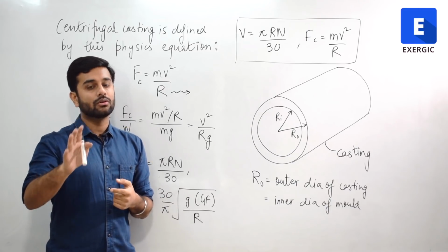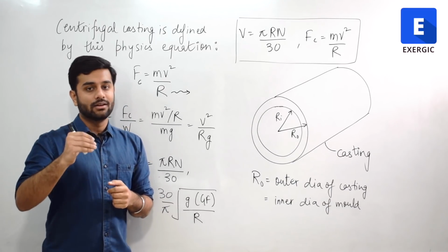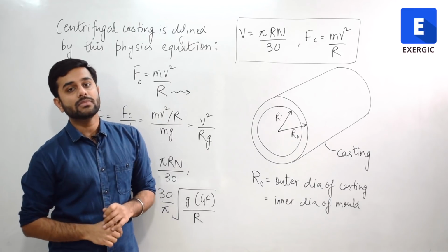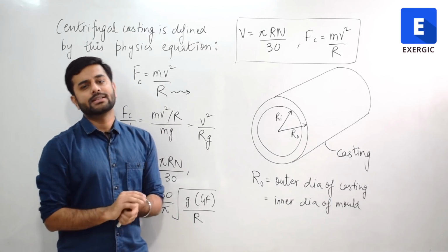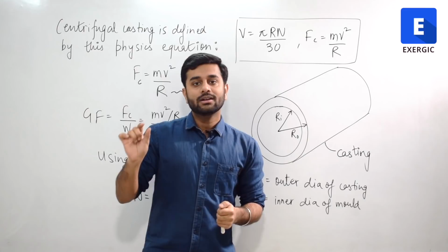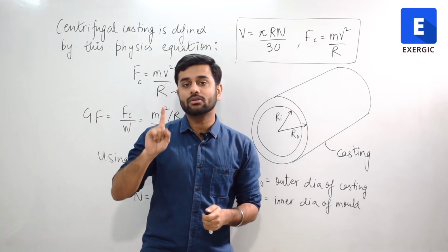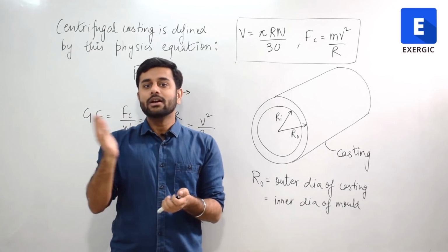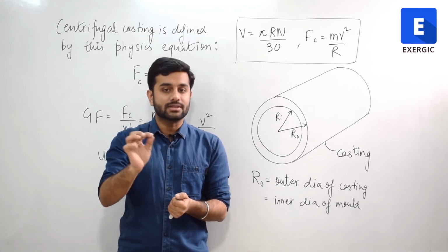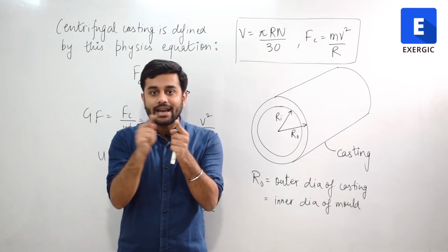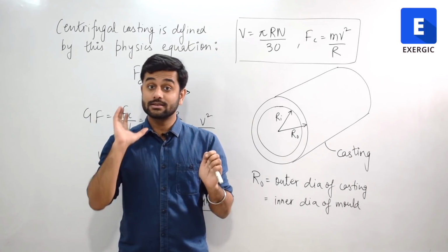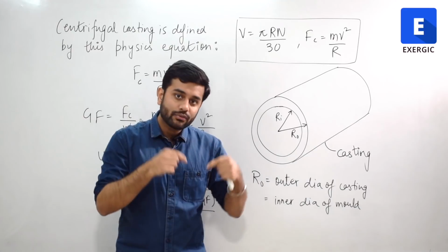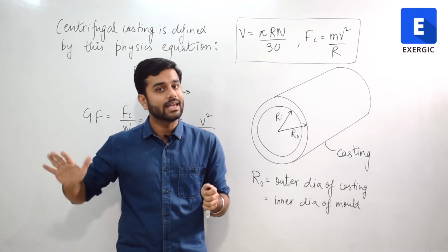Let me tell you the most logical way to proceed from here. The cylinders that we form are generally thin cylinders. We already know how we define thin cylinders, right? The thickness of the cylinder should be less than 7% of the inside radius of the cylinder. This is the same definition that I am quoting from roughly the same source and NPTEL.